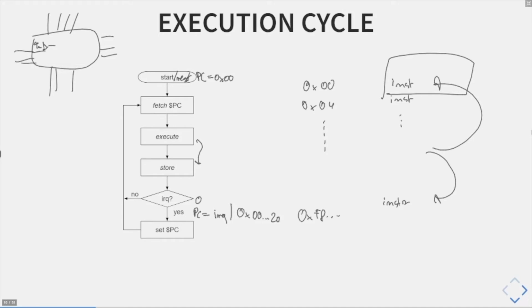And that's basically what should happen in this execution cycle. This is what you can assume from a normal CPU. No matter how your CPU executes those instructions, whether they are optimized, reordered, pipelined, or something else, this assumption is true for all of them. You start at some point and execute whatever your program counter says. If there is an interrupt between two instructions, you continue somewhere else, execute this briefly, and then return from this interrupt handler to the normal operation of execution. That's all that is happening, whatever CPU you are using.